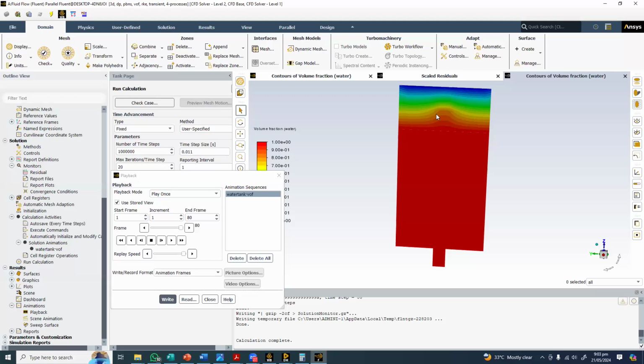I would prefer that it should be around one or less than one. In that case, as the size of the mesh reduces, so does the time step. So we have to go for a smaller time step. But for demonstration purposes, I have to compromise on the solution accuracy.